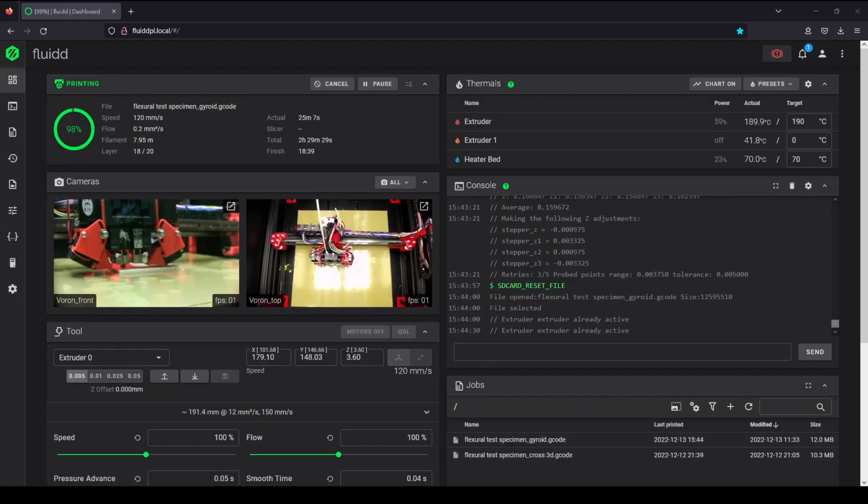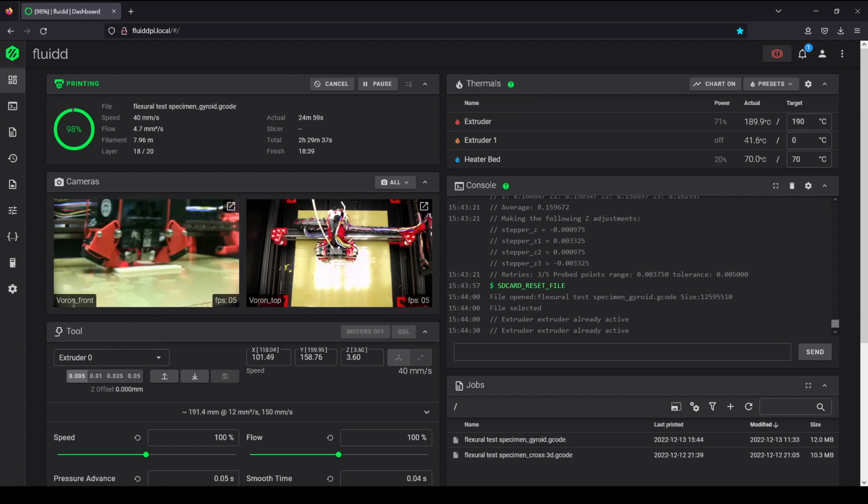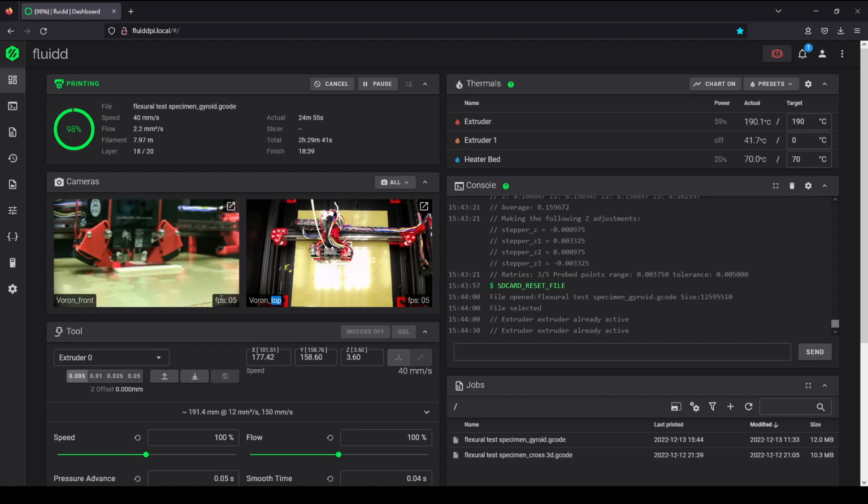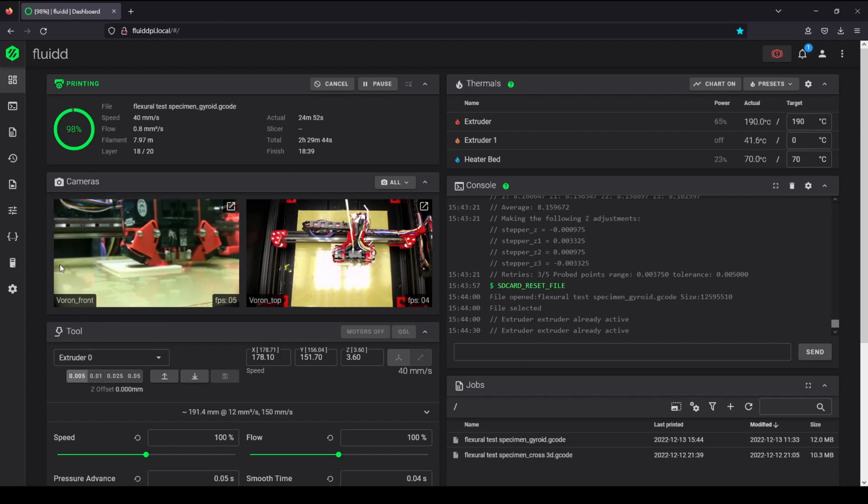I didn't check for the third one because only 2 cameras have already consumed a lot of Raspberry Pi resources. One for the time-lapse at the front and the second camera for overview on the top. I also checked the type of webcams. Some high-end webcams are not supported by V4L2, which makes them hard to set up on the Pi.